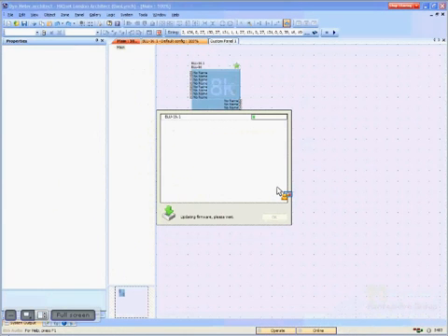By the way, here's your firmware update process for those of you who've never done it before. When you open up your design file, if it's from an old version, it'll say your design file's from an older version, do you want to update the file? And it'll warn you that if you update the file, you can't open it in old versions anymore. A design file you create today will work in today's software and tomorrow's software. It will not work in yesterday's software.